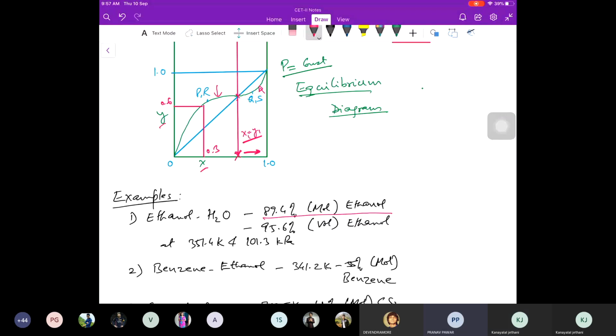Meaning, sir, we will take out all the distillate at the azeotrope point and not let it go beyond that. That is the maximum we can take by simple distillation. There is azeotropic distillation, where you use another solvent, and then you can get 99% ethanol also, which is what is normally practiced in industry. If you want 99% alcohol, you do azeotropic distillation or some other form of distillation. But by simple distillation, as we are seeing, you can get maximum 89.4% ethanol. There are other methods to solve this problem. It's not that the problem cannot be solved, but not by simple distillation.